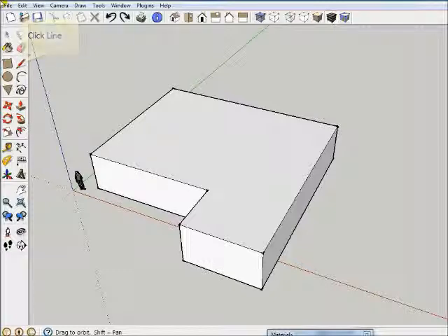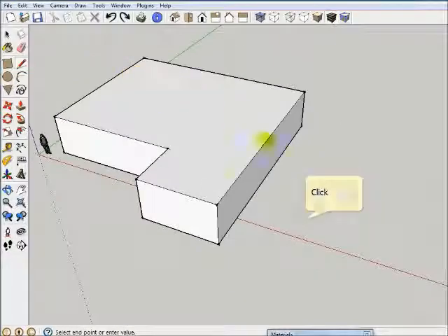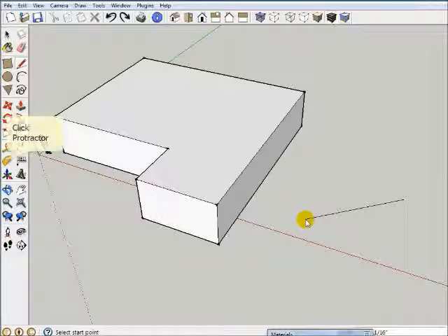One thing I missed in SketchUp, but I had in AutoCAD, was the ability to kind of draw a line. That's x-axis, no problem. That's green axis. But if I wanted a line at 45 degrees, in AutoCAD I could say @ 20 feet at 45, and AutoCAD would put that angled line in there just like that. In SketchUp, the workflow is a little different.